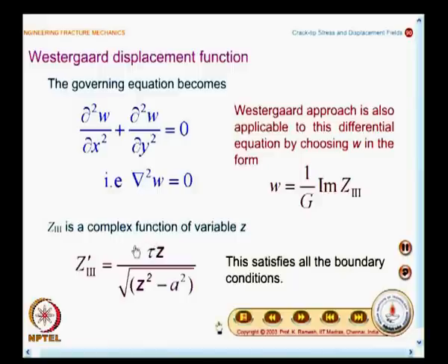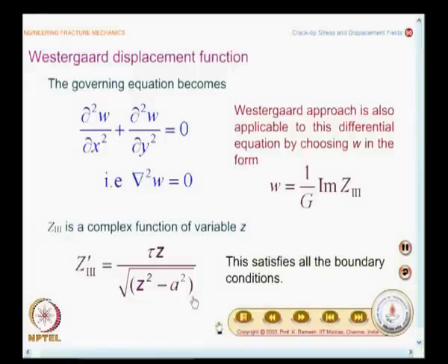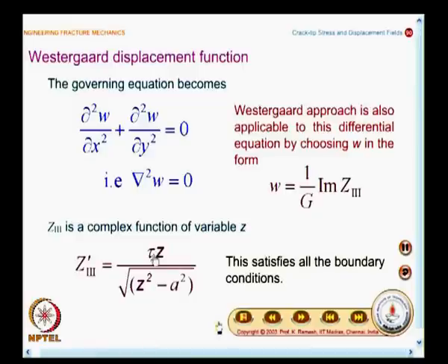From your understanding of the crack problem, you know this stress function is very similar to what we have seen in mode 1 as well as mode 2 loading. There we coined them as stress functions. Here you are using a similar form for defining the displacement, and you have to take note that this shear stress is out-of-plane shear.